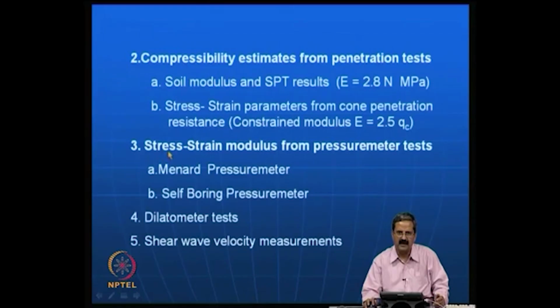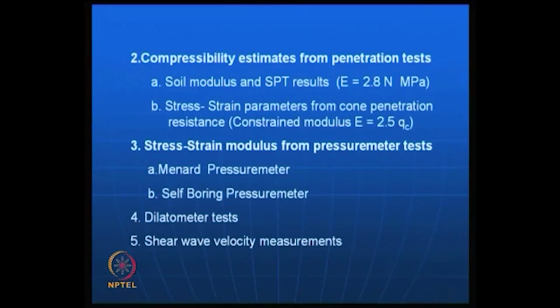There is another equipment that we use in a very nice manner, which is called the pressure meter test, in which you have a small tube with a diaphragm. Once you insert it, it expands, and then you try to find out both the deformation and the pressure exerted to create that deformation.